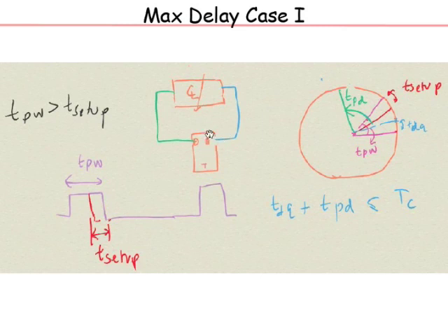There's a single pulse latch, and you can use it for latch based design, flop based design, all of that. This is an approach to understand what's going on. Basically what I'm showing here is the latch output goes through the combinational logic and comes back. It's a cycle. I'm showing an arrow here where I can adjust the delay of the combinational logic. I'll start off with a very low delay and keep cranking the delay till the circuit fails.